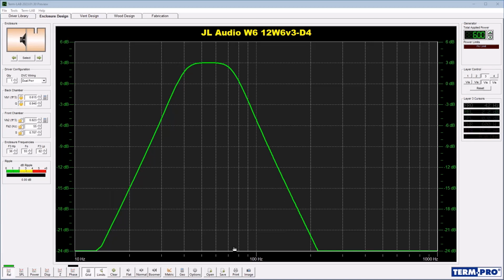This is how I like to envision that. If you imagine this green graph here as a solid piece of wire, and you take your left hand and grab this side, and you grab this side with the right hand, the length of that wire is fixed. If you move your hands together so that they're closer to one another, this right here will peak up, so you'll get more gain. But the bandwidth, so think of bandwidth as the distance between your hands, gets narrower. So the product of those two numbers is constant.